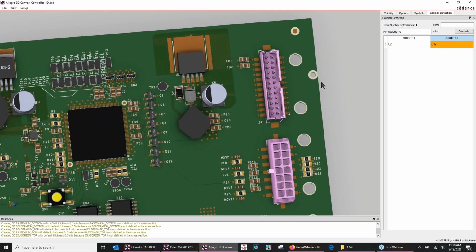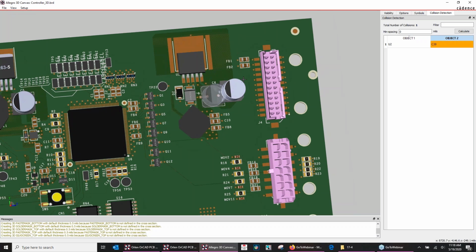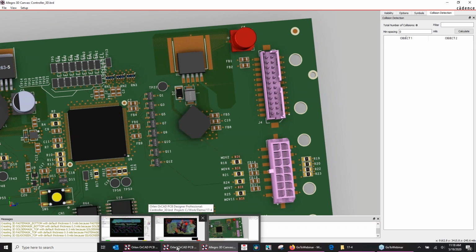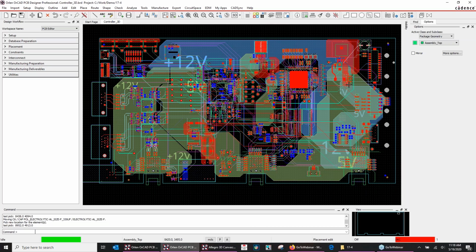engine, a 3D route engine. So what I could do is come in here and identify that part, and I could say move that part, and I could literally move that cap now and have it set up there. That cap has changed. Now I can come back here to my 2D model and notice my cap, of course, has a disconnection, you've got a rat's nest to it, but notice that my cap is now moved up here.